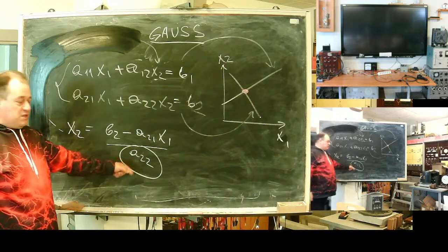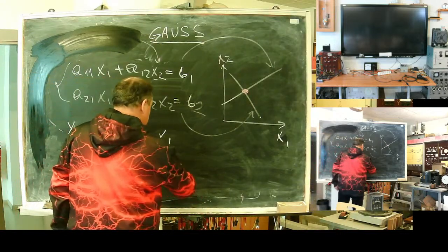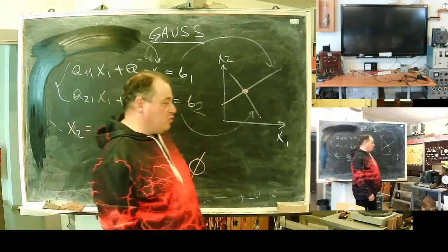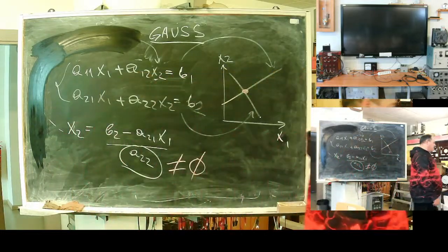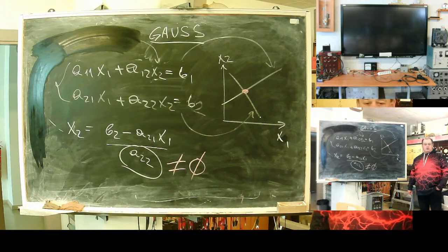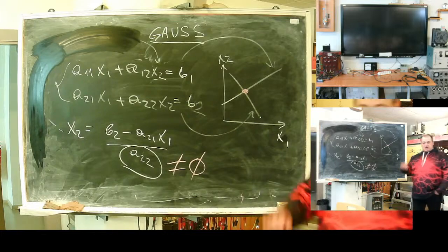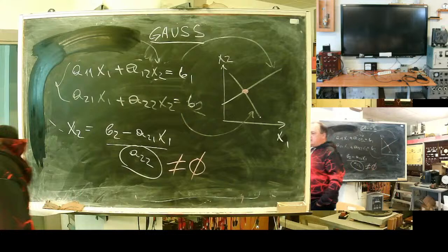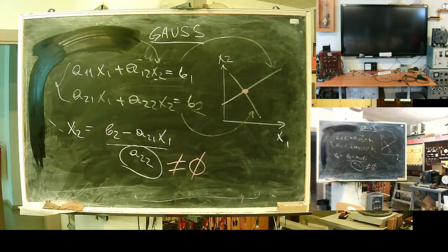It should not be 0. If you try to solve Kirchhoff's equations, oops, there are a lot of zeros. So you will need to reorder your system, reshuffle rows and columns to get the A matrix in a form that there will be no 0 on the main diagonal.